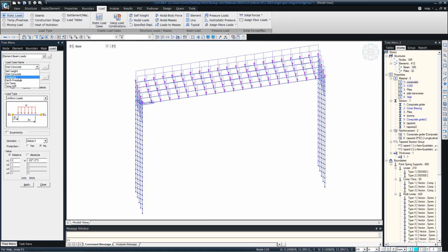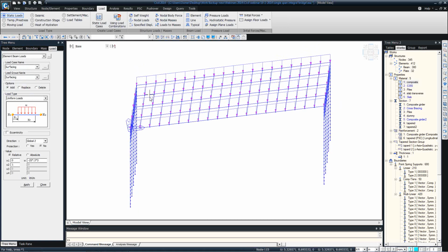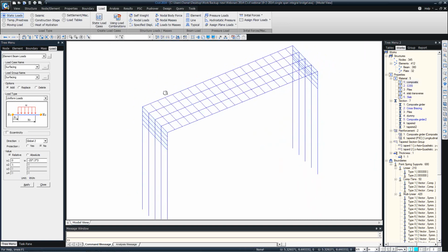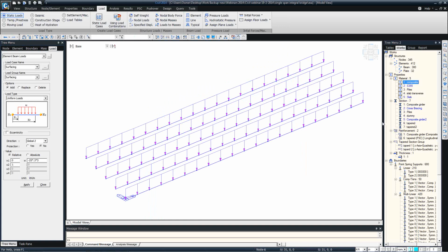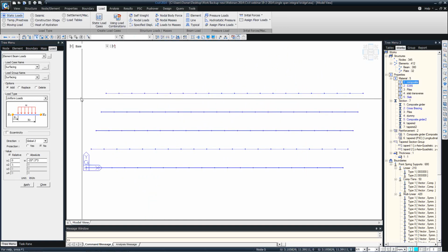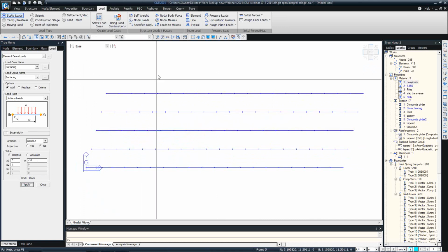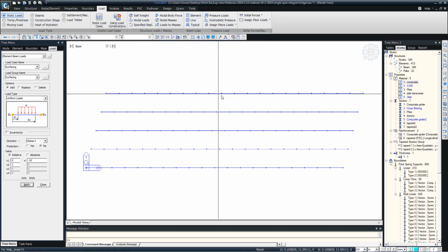The next thing is applying surfacing loads. Surfacing, we can select some of the internal beams and apply surfacing loads. You can apply surfacing as a floor load as well, depending on how you want to consider it. You can apply it as a UDL, so I'm going to apply it as a UDL in this example. So just selecting, say, these many girders and -10, for example, and apply.